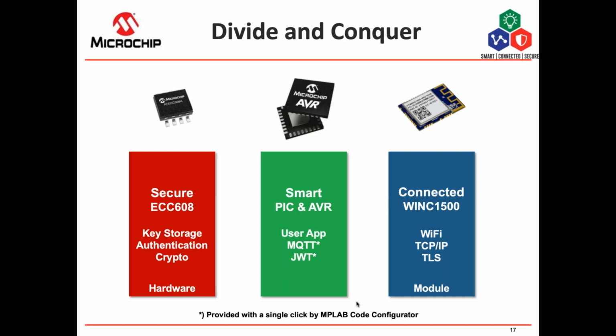So what it does is that it looks like a small EEPROM for you, but it is designed to store the keys securely. So please don't put your keys for your crypto inside the flash of your microcontroller. Please don't do that.